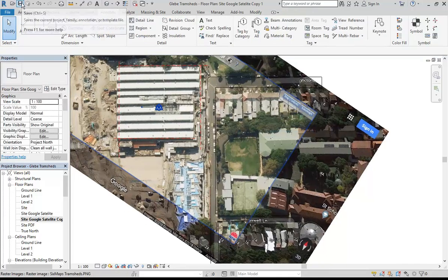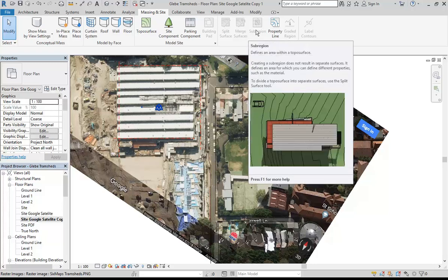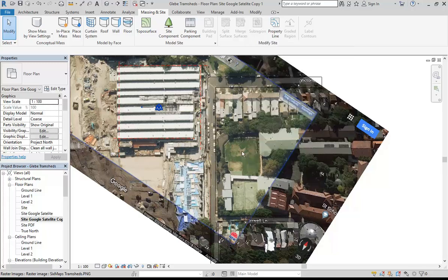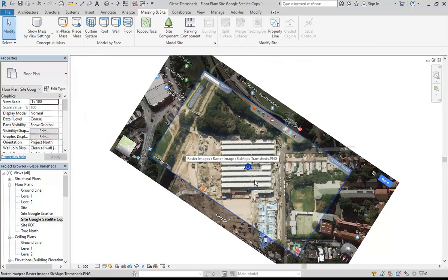And as I'm drawing, I can save the file, which might not seem like a very big thing, but trust me, when you're doing it with sub-regions, you can't save midstream. You have to finish the whole thing before you can save it. Yeah, it's the worst thing in Revit. But that's how all those sketch mode things are. Can you go and make sub-regions out of the areas that you've drawn? Yeah, that's the whole point. Draw it first and then just trace it.